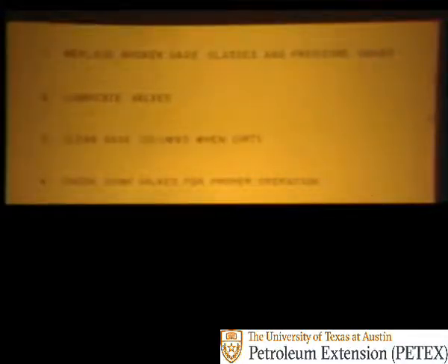3. Clean the gauge column sight glasses so you can know where the separator liquid level is. Gauge glasses can easily be cleaned internally with a gauge glass brush, water, and a detergent. 4. Periodically check the dump valves. Stroke the valves by holding down or lifting the controller flapper to make sure that the dump valves are free throughout their full operating range.